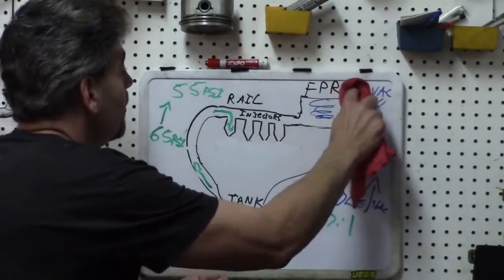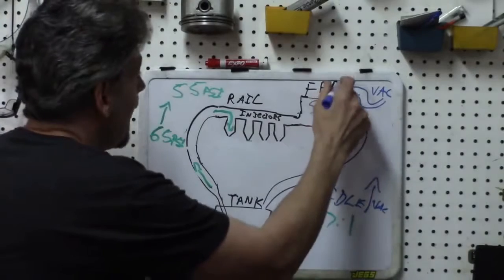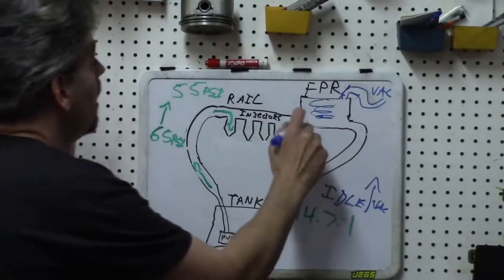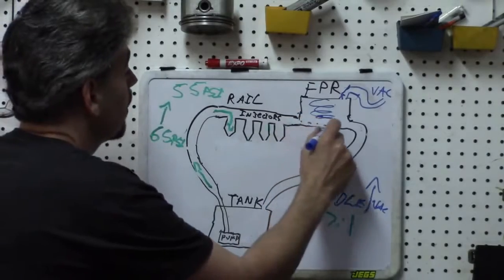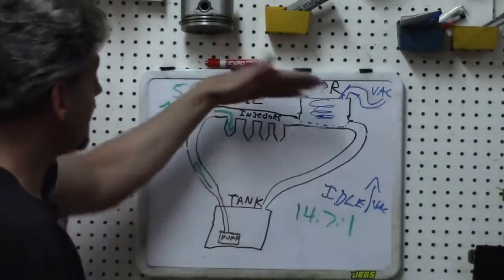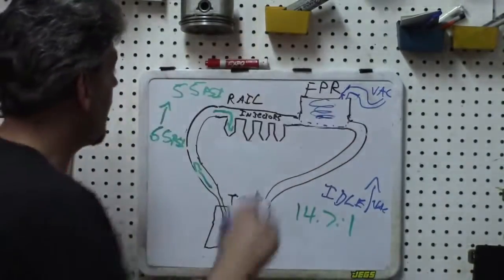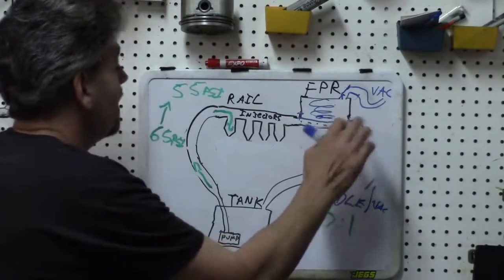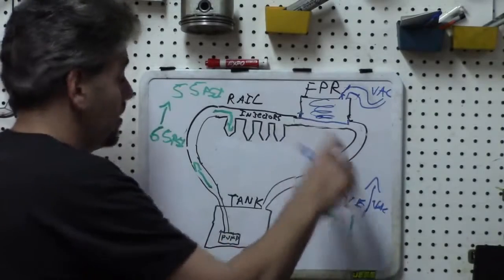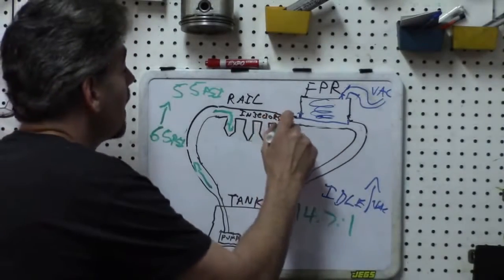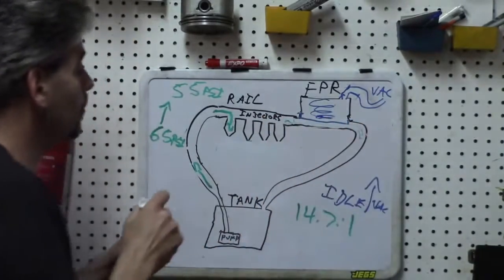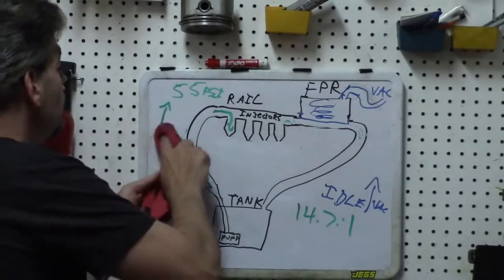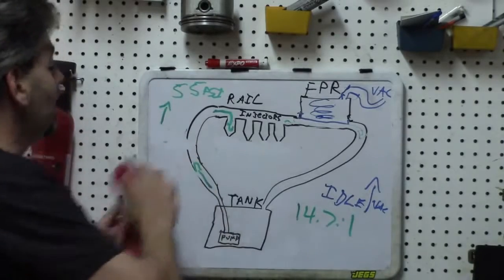All right, let's do this. Let's go ahead and, at idle, reconnect the hose. What's that going to do to our diaphragm? When we reconnect the hose, it's going to suck up and counter the spring and pull that diaphragm back to its original condition, allowing that flow to increase through the return. And of course, we will go back to our usual PSI at idle.